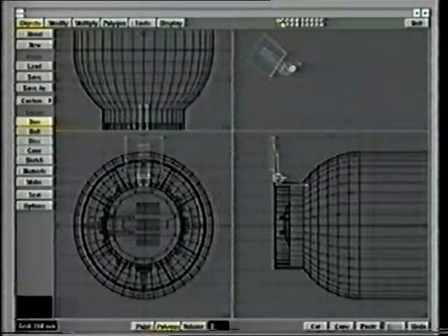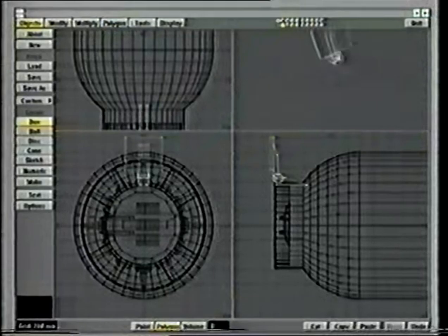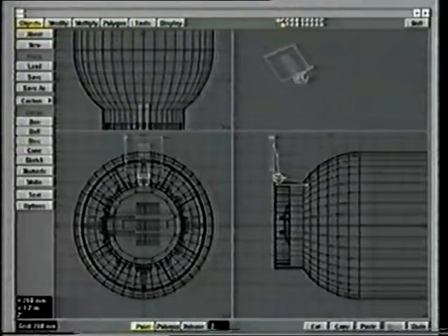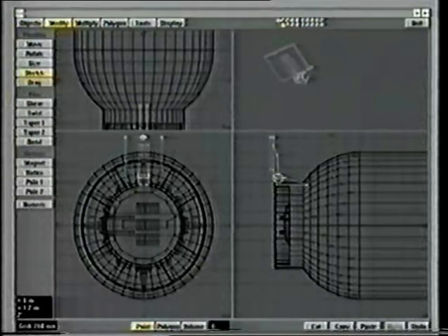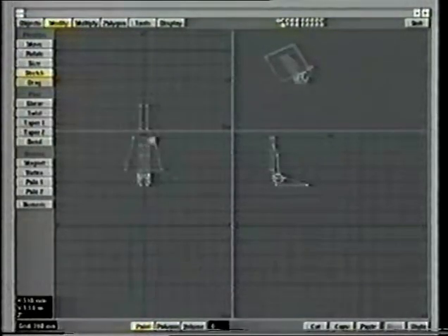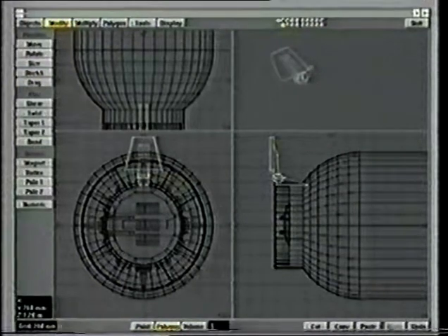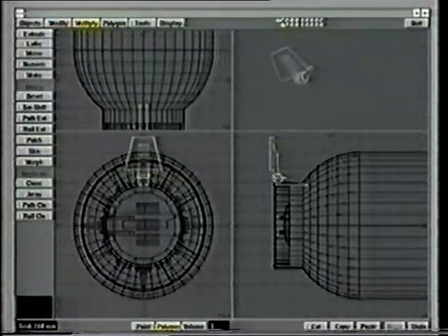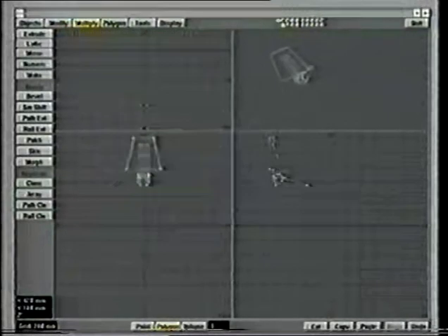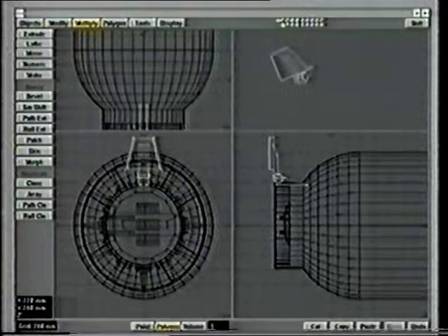Now, as it stands there, it kind of looks a bit goofy. It looks like a signpost or a weird bat. So I'm going to taper it towards the top just by selecting the points on the top of the box and then using stretch with again the cursor in the middle, control key to constrain it. Okay, that looks like something now. And let's just take the face polygons and not the edge polygon and do a bevel. And that looks okay. That should be fine.